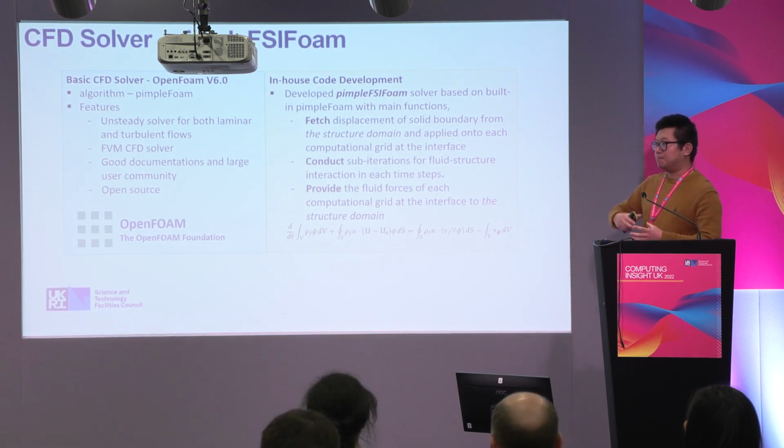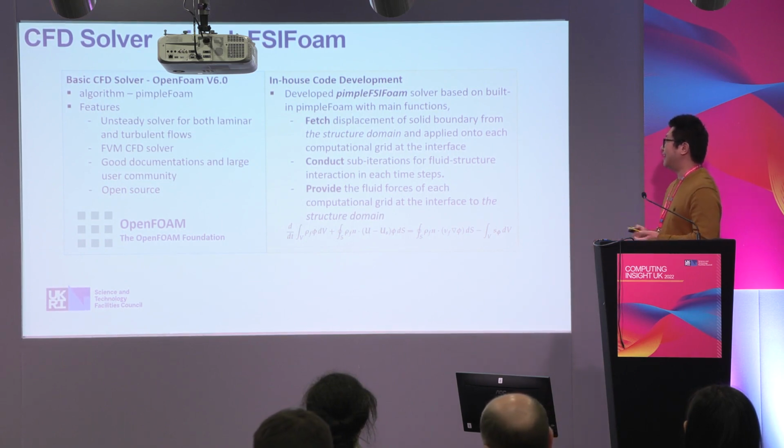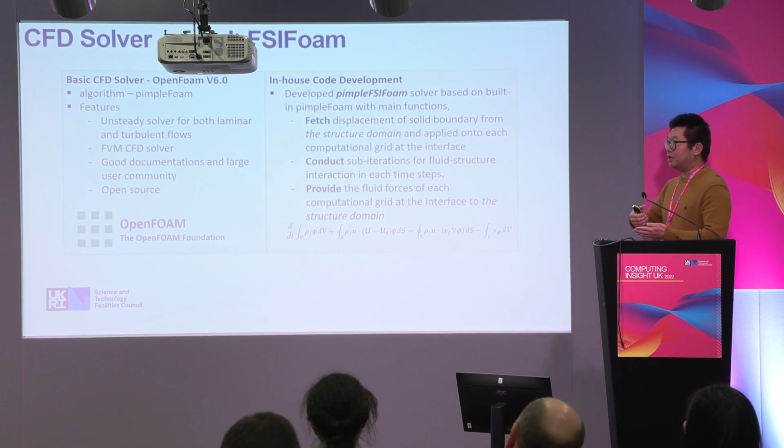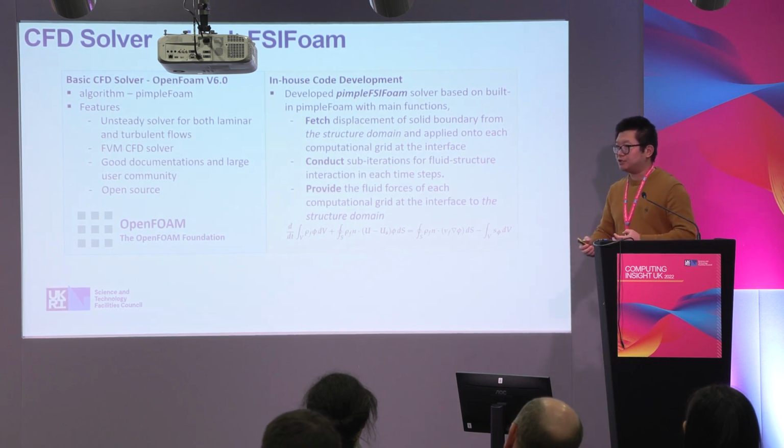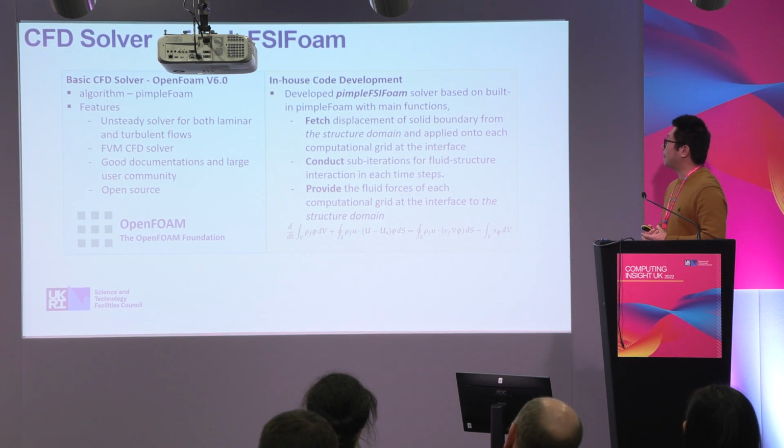The extension fetches the displacement information and applies it to the fluid structure interface inside the fluid solver, and provides the fluid forces in each element, in each cell, and pushes that information to the structure domain.